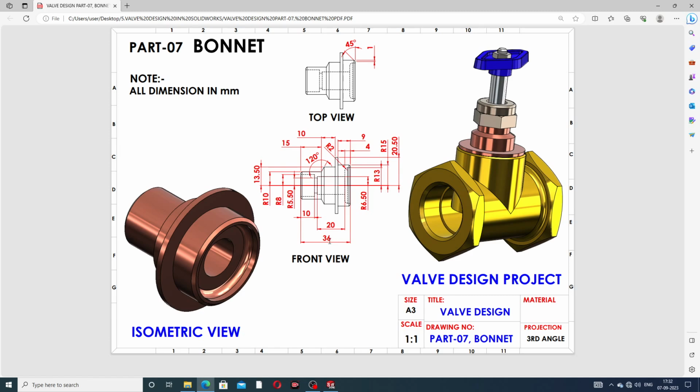And at first drawing, the full length is 36 millimeter, and this length is 20 millimeter, and this length is 10 millimeter. Okay, this is the upper length, and this line is a reference line, and this is the axis of revolution, and revolve boss base is applied to this body. This half body geometry is dimensioned, and revolve boss creates the full body here.